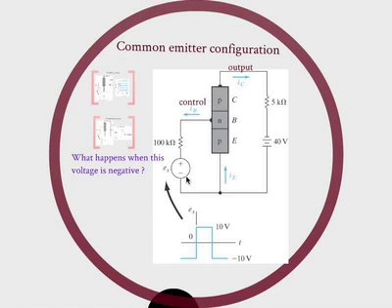Wait a second. So my mistake. So I guess I wrote it the same way. But okay, let's follow the logic. So if it's negative, it should be forward biased. Okay, does everyone see that? Yes, right? Okay, because N is connected to the positive terminal, P is connected to the minus terminal in this case. So if the voltage is negative, it's forward biased. And that's normal operation, right? Because you have a forward biased junction between the base and the emitter, you expect injection to happen.